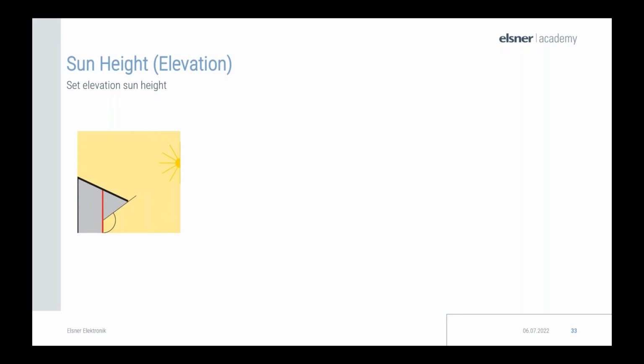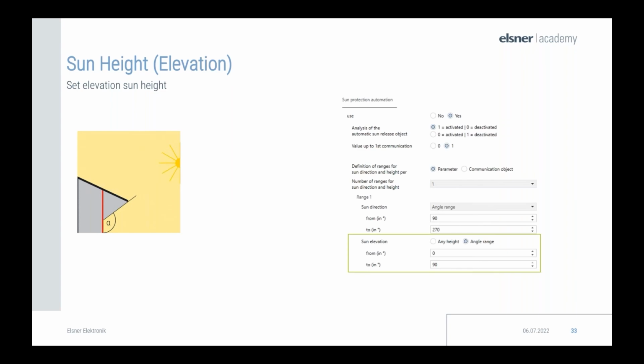Before that, it's not a natural cast, but the cast of the shadow from the building shape. So the values entered in this green box here help you to set the parameters right. Basically the shadow edge, you can see in this photo, is around 53 degrees, so shading is only activated once the sun surpasses this point.